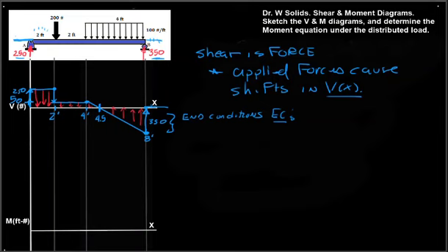Now let's start the moment diagram. When we're sketching a moment diagram, you'll often wonder how much room do I need below for the negative moments that I might have. And there's an interesting way to keep track of that. It's by deflection.